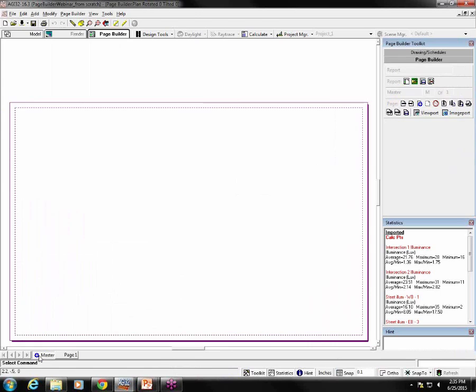But it also must be saved in model space in AutoCAD, which is not the standard location for title blocks. So let's assume that you have created a title block in AutoCAD. It will generally be in paper space, but you'll need to copy it into model space. You'll also need to scale it to fit the paper that you'll eventually be printing on. That might also mean assigning units, feet, millimeters, or whatever. Finally, you need to save it as its own DWG file.